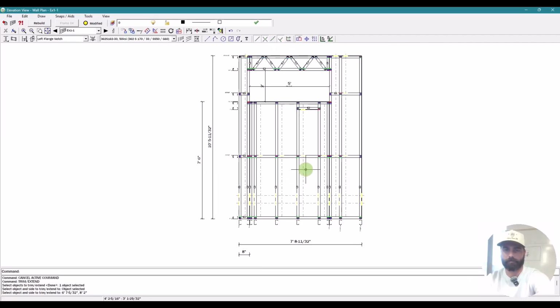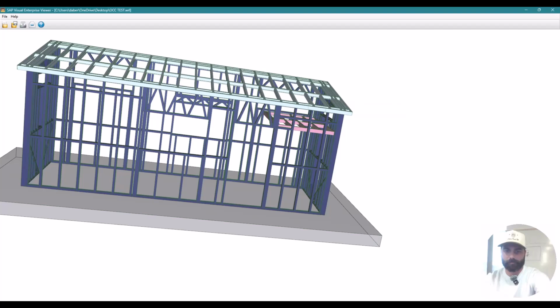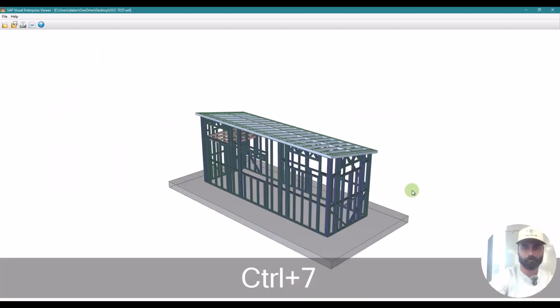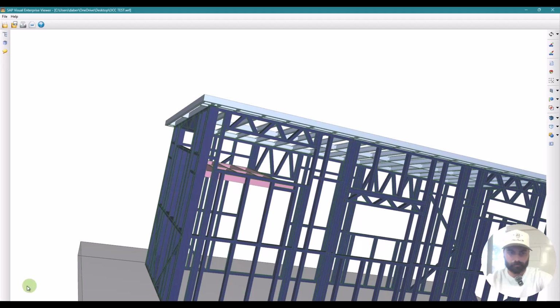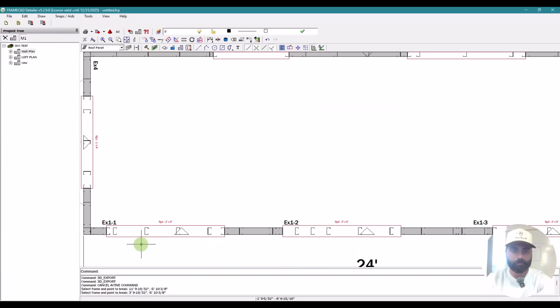We're putting some roof panels together at this moment, and yeah, the weight is astronomical, it's 683 pounds. We start using 18 gauge versus 20, 22. Remember, when you get your coils, there's a big range for 18 gauge or 20 gauge. If you get a heavy 20 gauge, it's as heavy as 18 gauge. You get a heavy 18 gauge, it's really heavy. When you're buying something by the pound, it makes a difference.